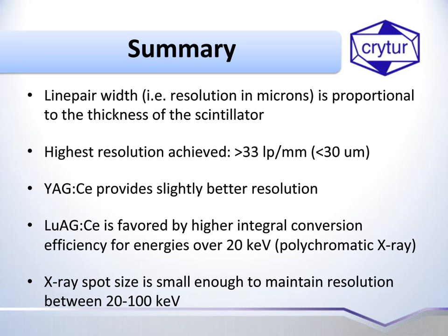Okay, great. Thank you. What solutions do you suggest to couple scintillators and camera detectors together? There are basically two solutions. The first would be using microscope objectives to couple the scintillator to a CCD camera, or the second would be using FOP, as we are talking about today.